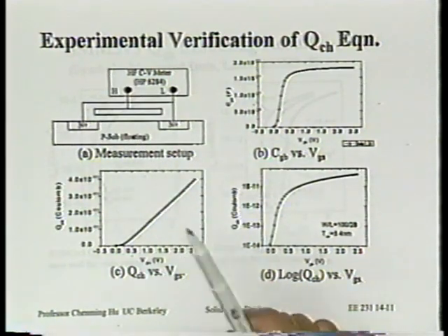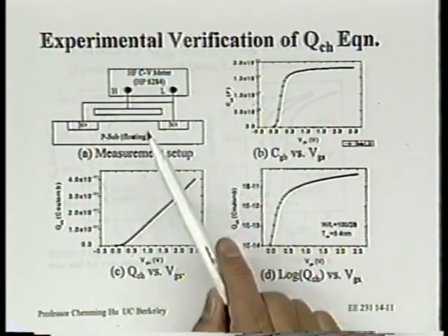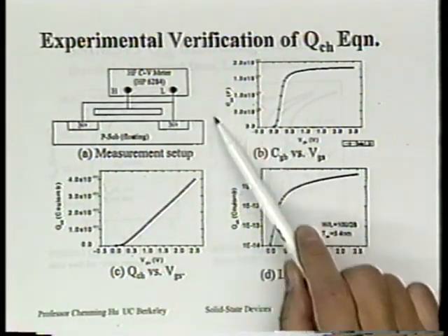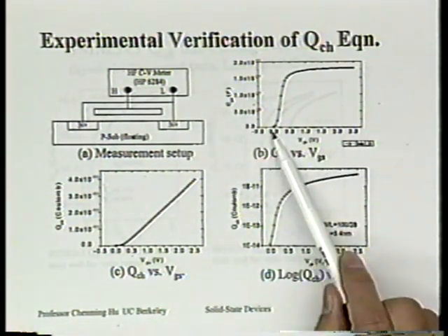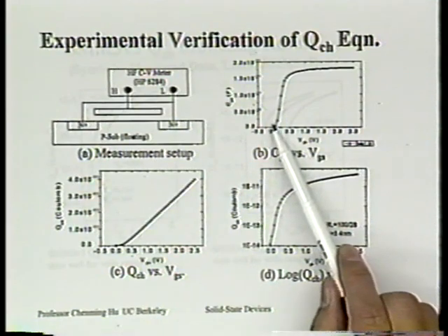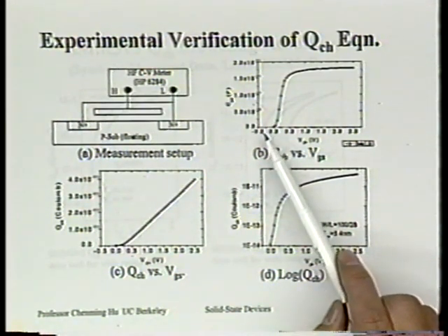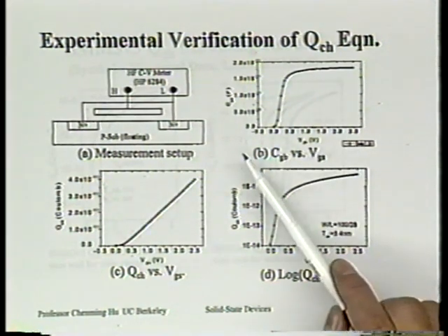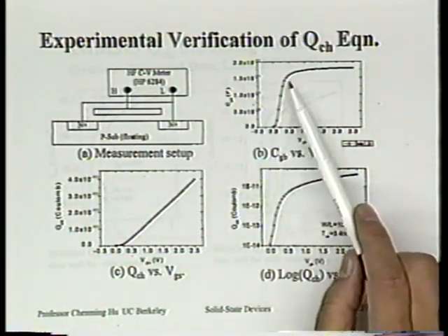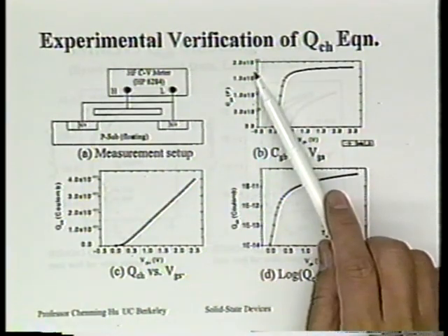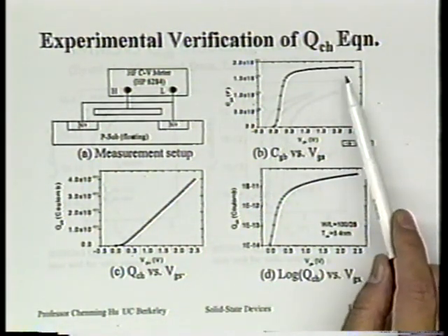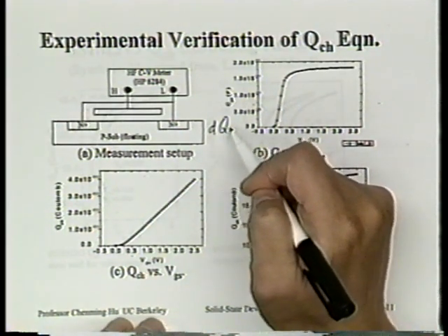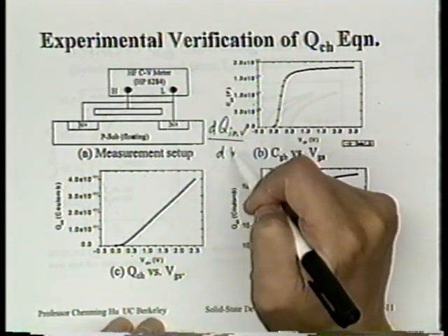It's very easy to deal with the overlap capacitance. I'll remind you in a minute. You end up with this curve, the capacitance versus VG. You don't see any capacitance until you get to threshold voltage, or close to threshold voltage. And it rises gradually. There's no assumption about suddenly getting inversion charge. It just gradually rises until you eventually saturate at Cox. So this is giving you the channel charge, the dQ inversion/dVG. That's what this data is telling you.